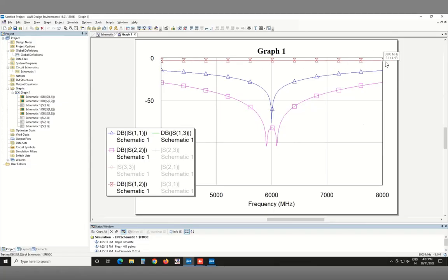Now, this, of course, is still very ideal because the transmission lines and everything have no loss. When you make something on a circuit board, that will have some insertion loss, so that will add to the overall transmission losses. You won't get exactly this. But that's why this circuit is actually very, very popular. It works quite well for a reasonable range of frequencies, right?